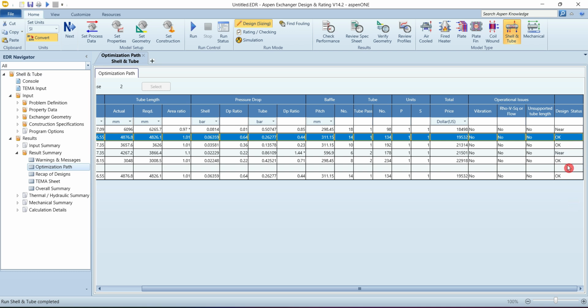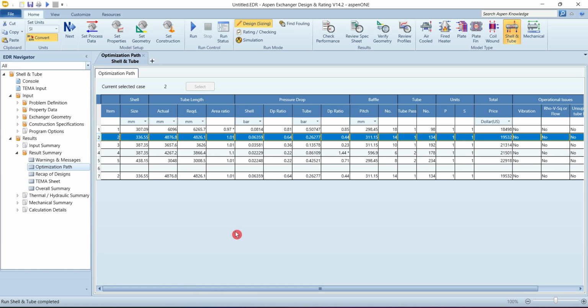last options were perfectly fine with respect to the quick checks and with respect to the hidden feasibility checks. And it has taken the first option, that it is pretty sure that this is the most feasible option. So that is not the most economical one, but the most feasible one next to the economical one. So this is how Aspen Plus makes different calculations and displays one of those results.